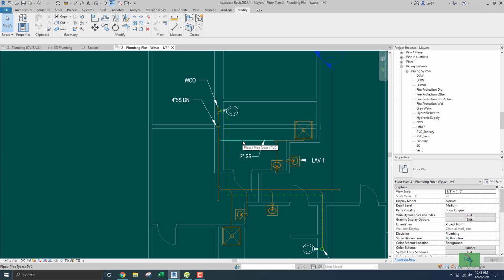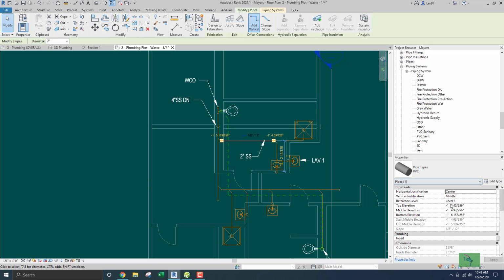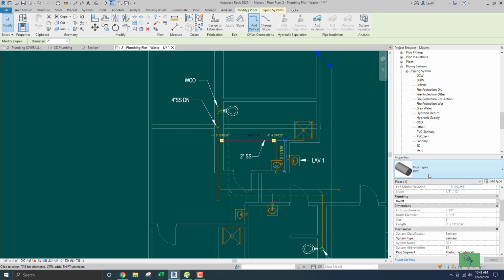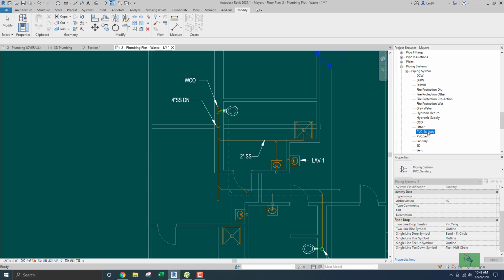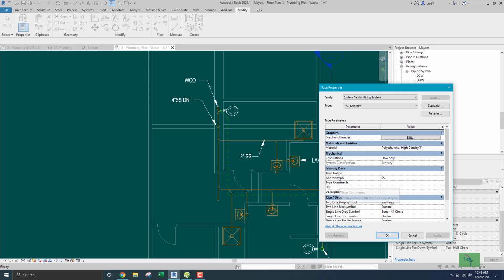Let's click here, PVC, system type PVC sanitary. Okay, let's right click on this guy, type properties. Yeah, here we go.